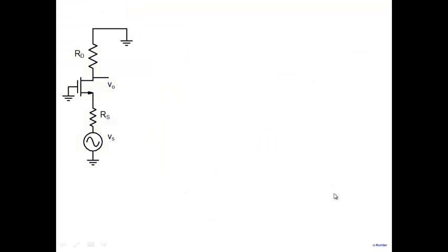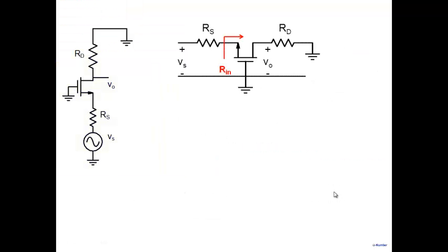R0 equal to RD here. And input resistance is what is very small. Now input is being applied at the source, and when you look into the source here, you can easily show that the input resistance is given by this expression here: (1 plus RD by R0) over (GM plus GMB). And RD by R0 is typically small. R0 is usually a much larger quantity than RD. So this is small. So input resistance is primarily 1 by (GM plus GMB). And this is a small resistance.